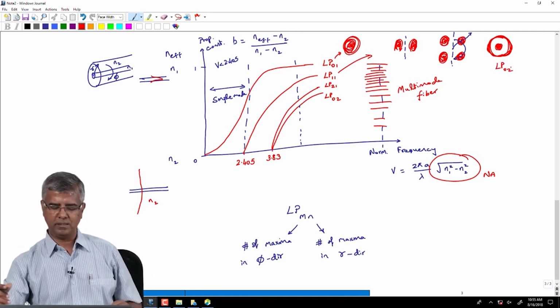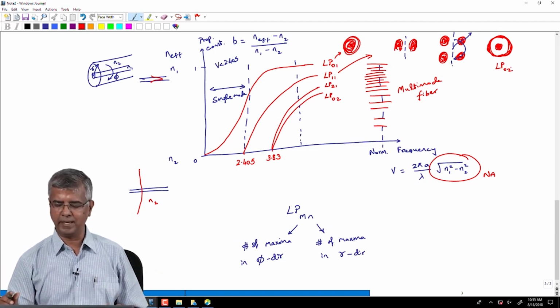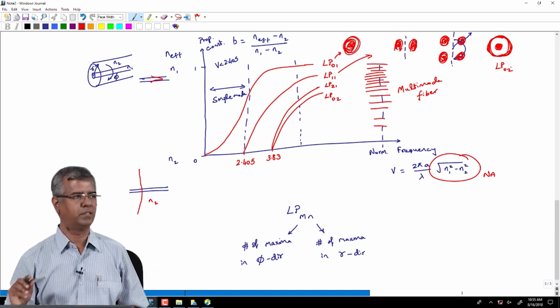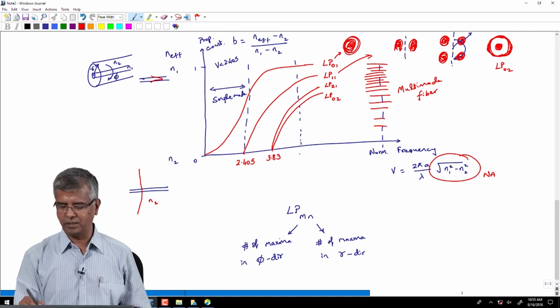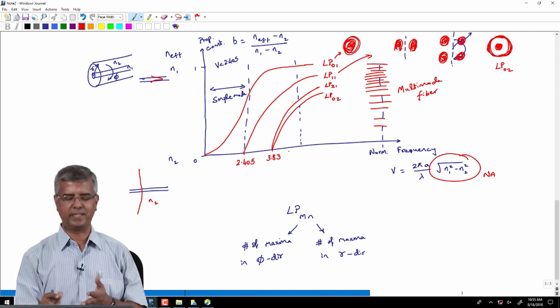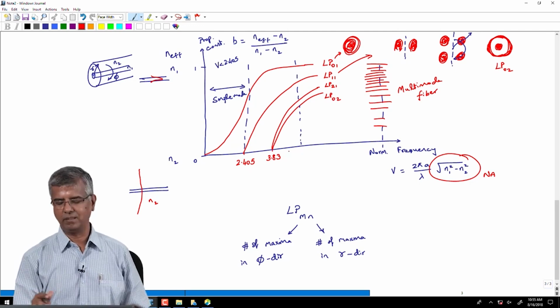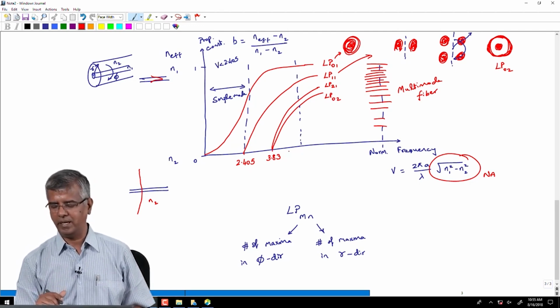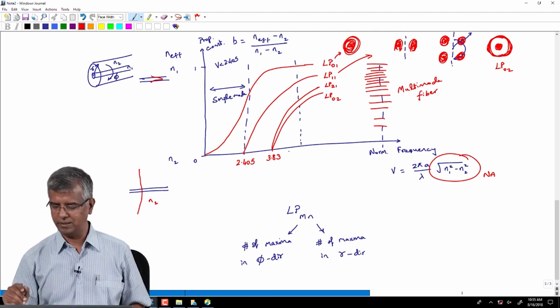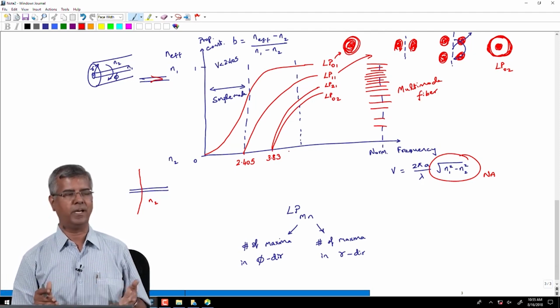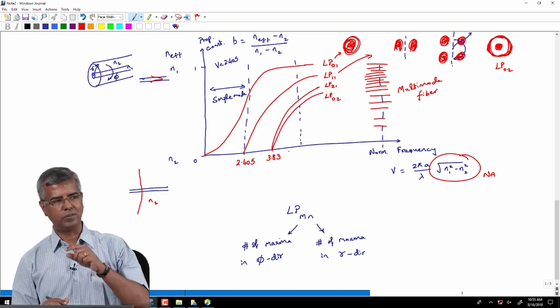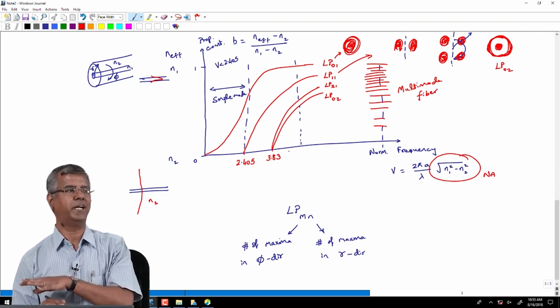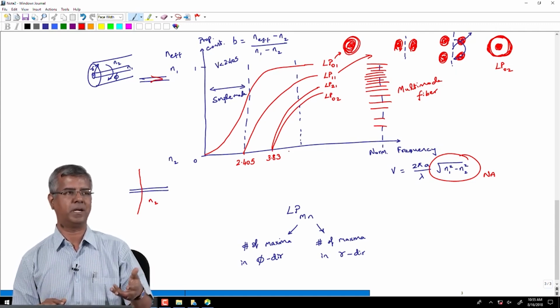And what we will find is, this is not just some vague theory; you can see all these modes if you choose a fiber whose V number is greater than 4. And what we see here is that the V number is not a defined quantity for one specific waveguide. For any specific waveguide, you have 2A and this NA defined, and those are all material parameters and structure parameters.